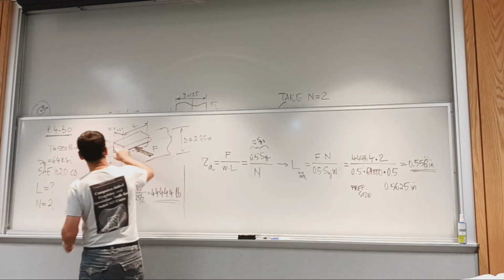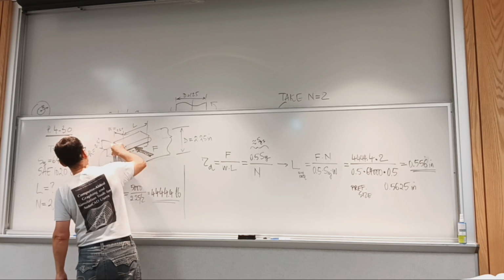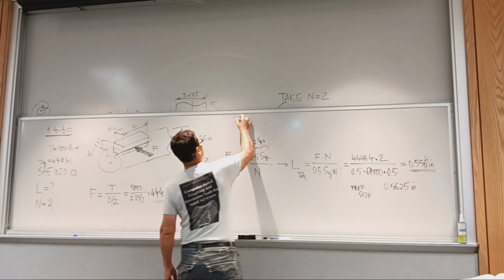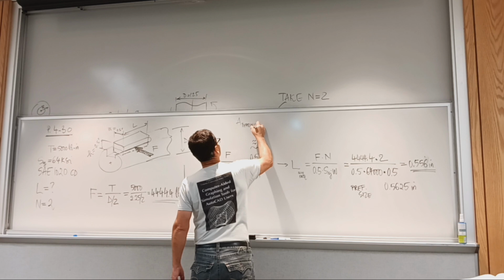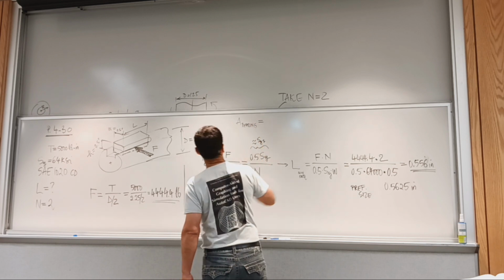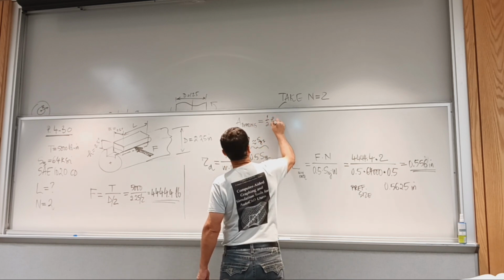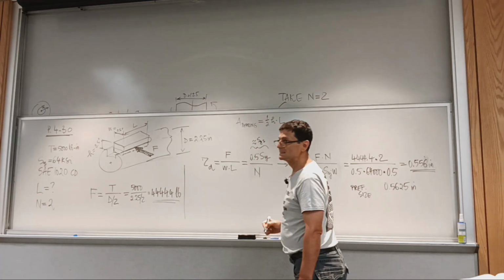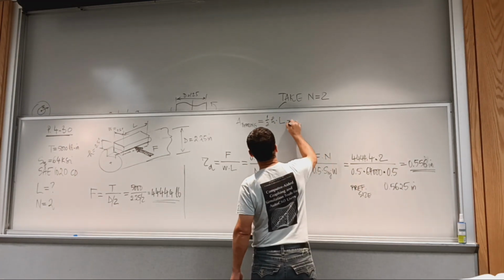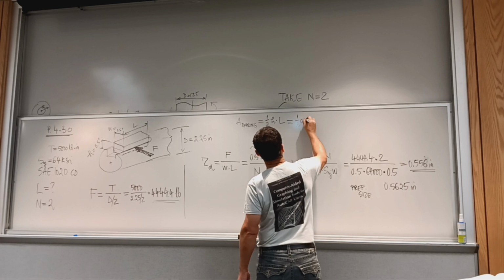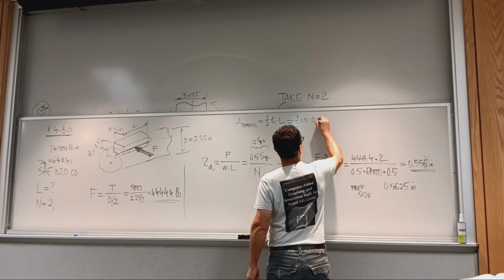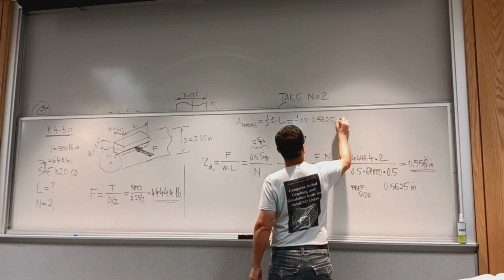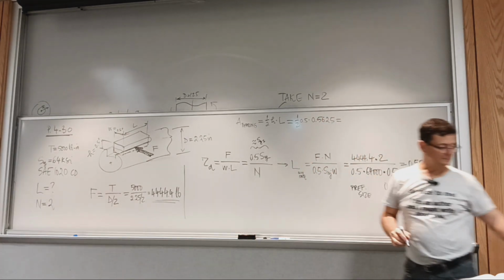Okay. But in either case, the bearing stress area is going to be, so area bearing, half of the height, 1/2 height times length of the key. Okay, and now I have a length, so we can calculate it. It's going to be 0.5 times 0.5 times 0.5625, and these will be inches squared.